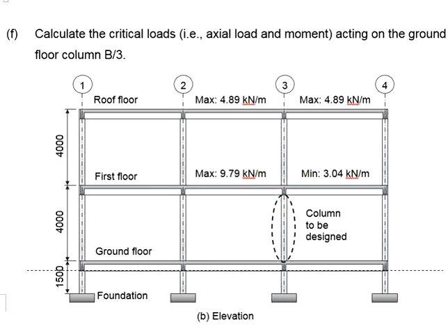This balance moment at the joint shall be shared by all the members of the joint. In order to determine the amount of moment taken by each member, we will need to determine their stiffness. The larger the stiffness, the more moment taken. Since we are interested in the moment taken by the column at this end, we will need to first find